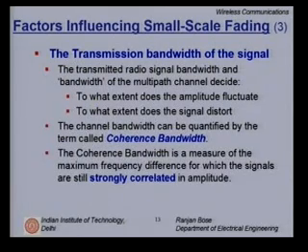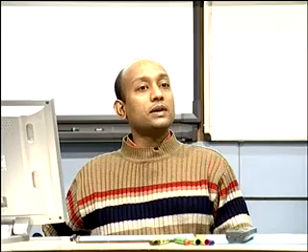That means, suppose I send a continuous wave at frequency f1 and it undergoes fading. That is, the received signal strength is much lower than what I sent simply because it is faded. So, I slowly increase my frequency from f1 to f1 plus delta f. As I increase my frequency, I decrease my wavelength. Now, at the receiver, what I receive and add up vectorially is different when I transmit my signal at a different frequency.